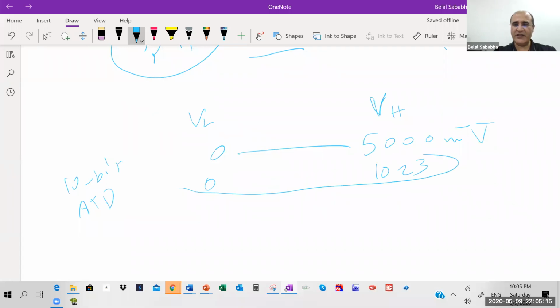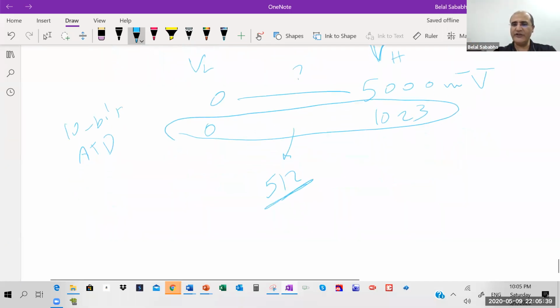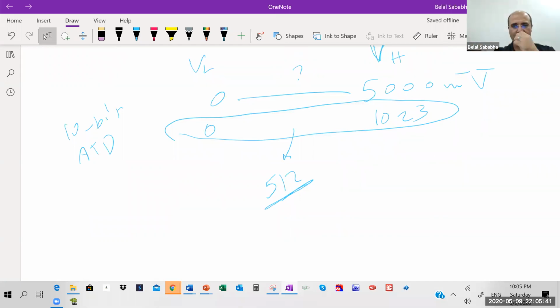Okay, you wrote a program that converts using an A to D. This is what you read inside your program. You said read the A to D, read the voltage on pin number port A0. You're going to read a number here. Let's say 512. What does 512 mean for the voltage outside? You need to know it to be able to convert voltage to temperature from the datasheet. How do we compute it? If I know the reading here...